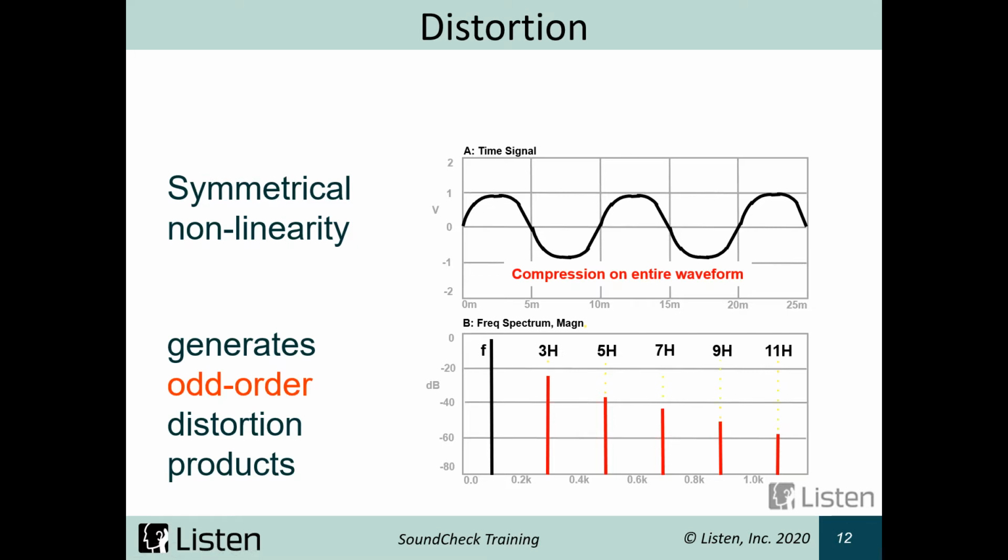In the real world, we're never going to just have even or odd number harmonics. We're going to have a mixture of both. But how much energy lives in different parts of them, if there's more energy in the second and the fourth than the third and the fifth, that could tell you something about your device. It could be some manufacturing defect that you need to catch. It could be something about the design. But it's going to tell us information about our device because of what harmonics are coming out when we input a single frequency.